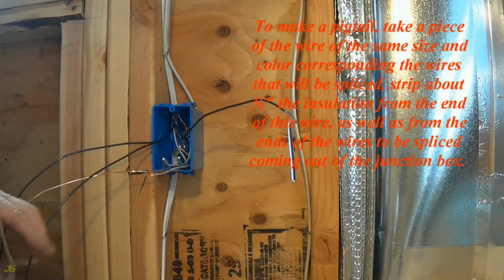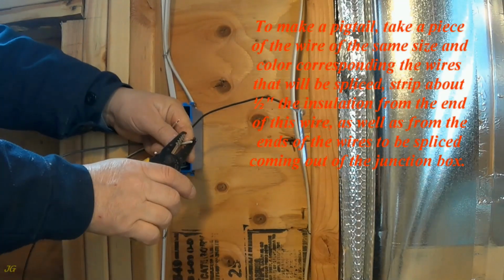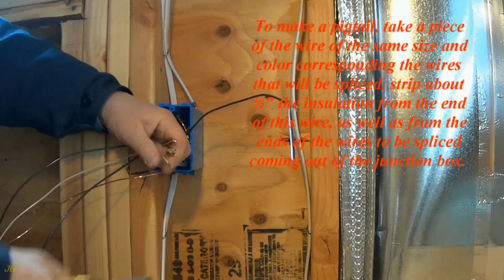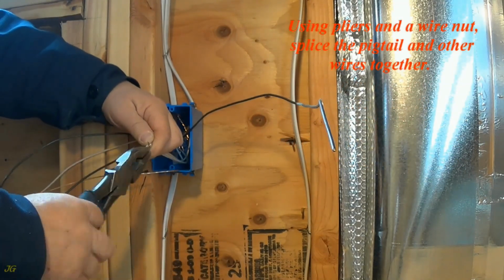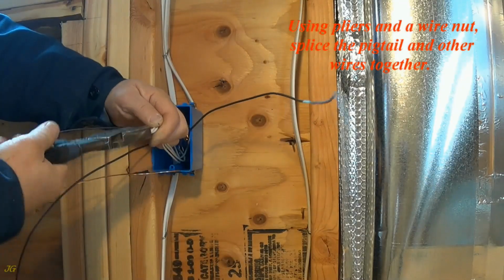To make a pigtail, take a piece of wire of the same size and color corresponding to the wires that will be spliced. Strip about 1/2 inch of the insulation from the end of this wire, as well as from the ends of the wires to be spliced coming out of the junction box. Using pliers and a wire nut, splice the pigtail and other wires together.